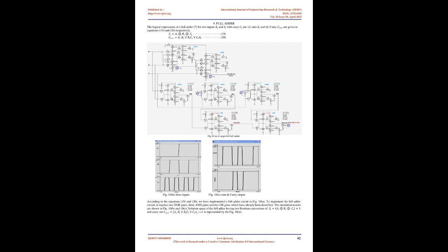If the value of the weighted sum is greater than the threshold or critical voltage value, then the logic output of the LTG will be 1, otherwise it will be 0. The tunnel junction capacitance and the output capacitance are considered the two basic circuit elements in a LTG. The input signal vector elements 1, 2, 3 are weighted by their respective vector element capacitances 1, 2, 3, and added to the voltage across the tunnel junction.